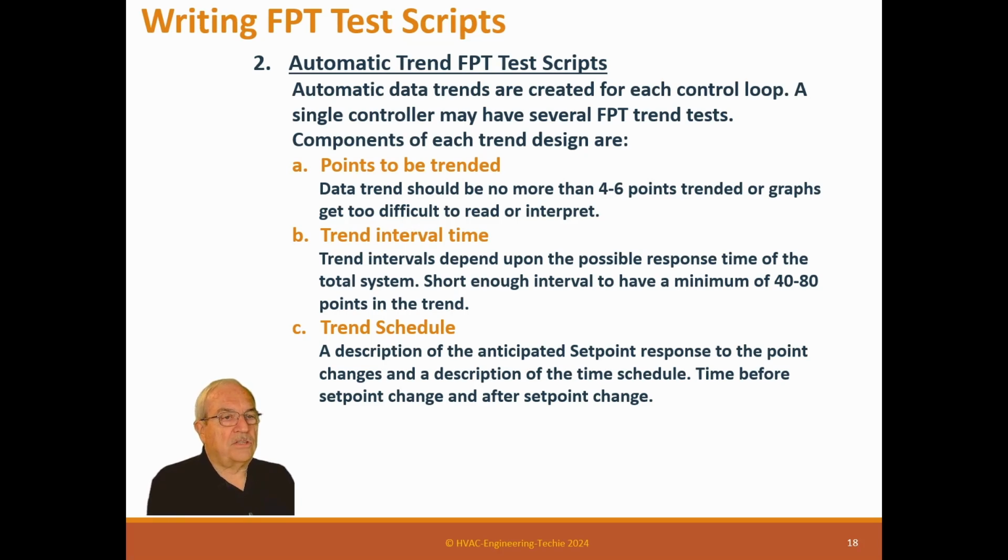Trend schedule, a description of the anticipated set point response to the point change, and a description of the time schedule. Time before set point change and after set point change. And we'll go over a couple of them so you understand what we're talking about. But these are critical things you have to put in your trend script.